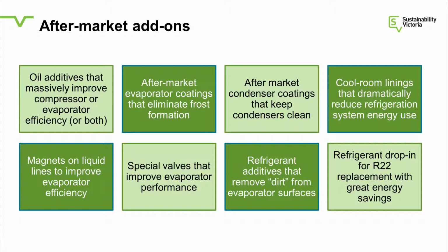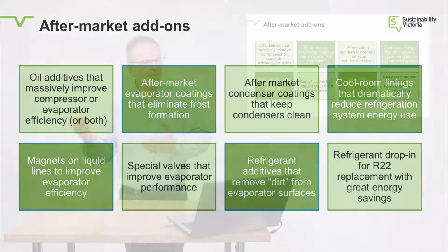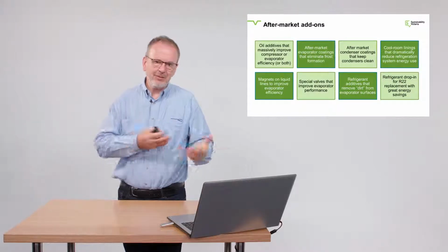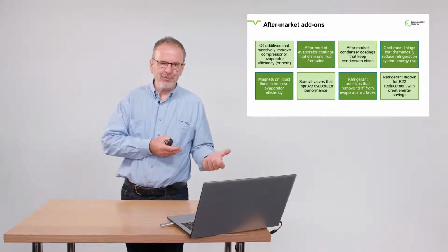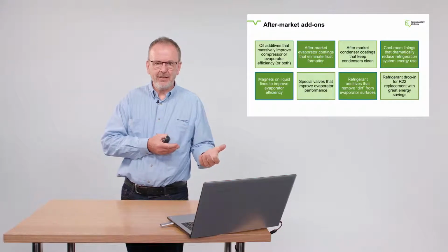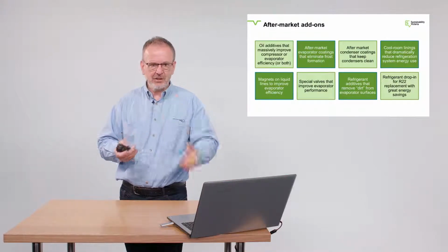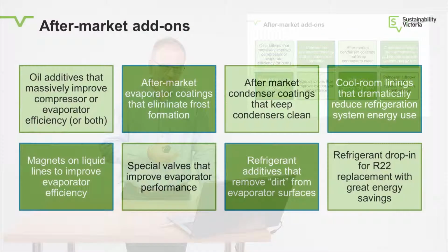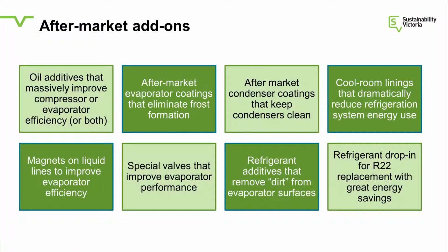Almost certainly it will. And very few of these oil additives, if any at all, are actually approved by any of the compressor manufacturers, for example. And the cleansing agents, the detergents that clean the evaporator, they may clean the evaporator, but they also clean the compressor and remove all the oil from the moving parts of the compressor. So neither of those are generally approved by any of the equipment manufacturers. So they may have a short-term benefit, but you'll probably be replacing your compressor very soon after.